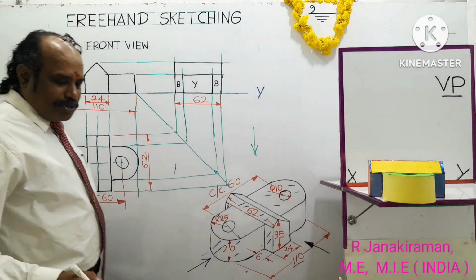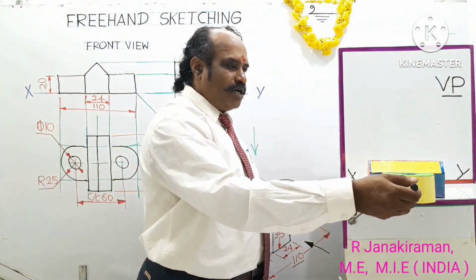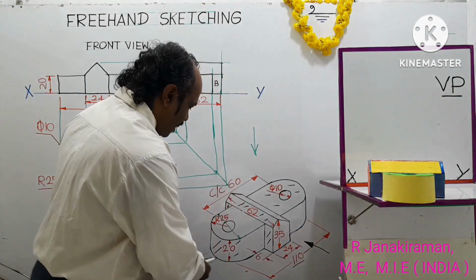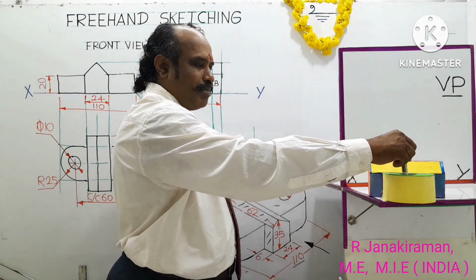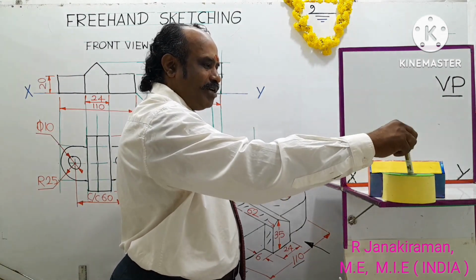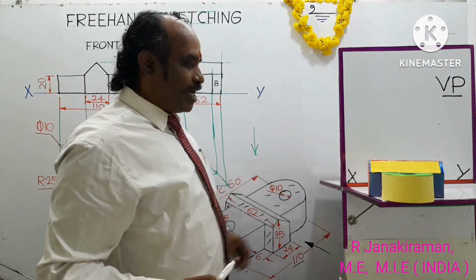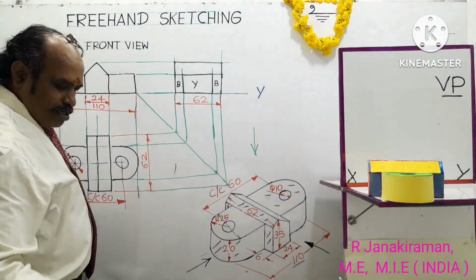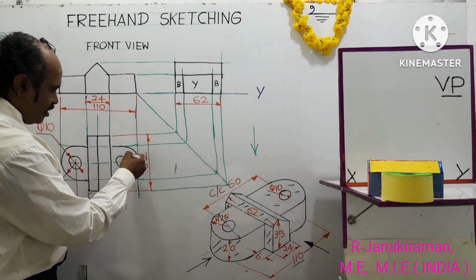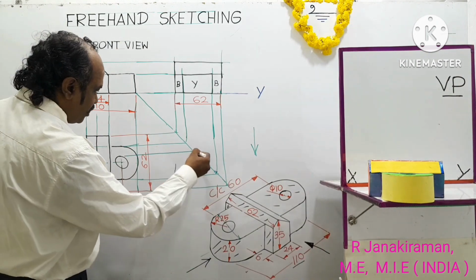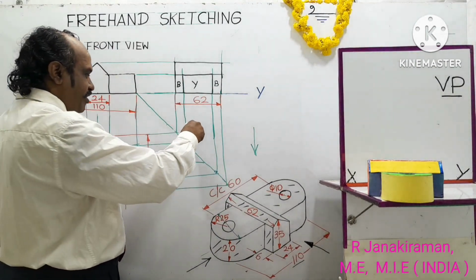So next, this hidden line is to be marked. This is the left side view, so looking in this direction, that is, this is that direction, the observer cannot see the hole passing inside the object. Cannot see. But something is available inside the object equal to the diameter of the circle. The smaller hole is to be shown in the diagram by means of a hidden line. So the diameter of the smaller circle is also projected. Where it intersects with the miter line, there you draw a vertical projector.